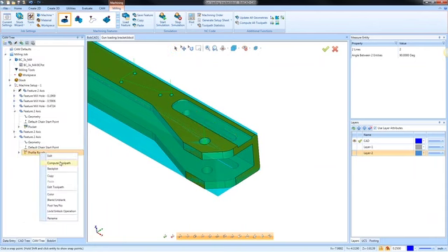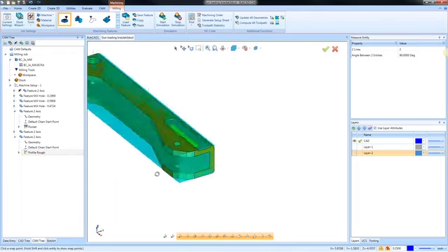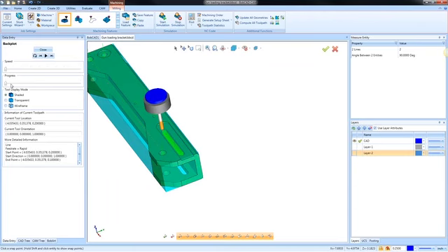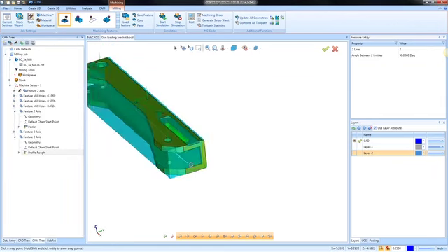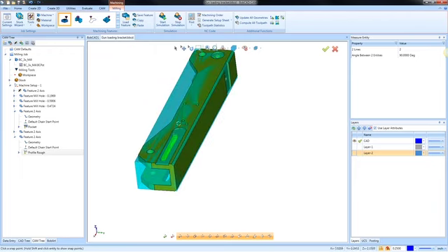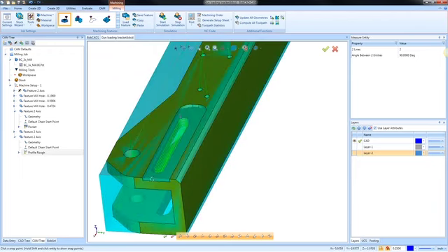All right. From here, I'm just going to recompute my toolpath. And then what we're going to see is a slotting type routine where the tool will work back and forth along this edge in order to create that slot there. Okay, so that is machining that side. Again, this is using contour ramping for a profile. So you have a profile and you can contour ramp. A great option.